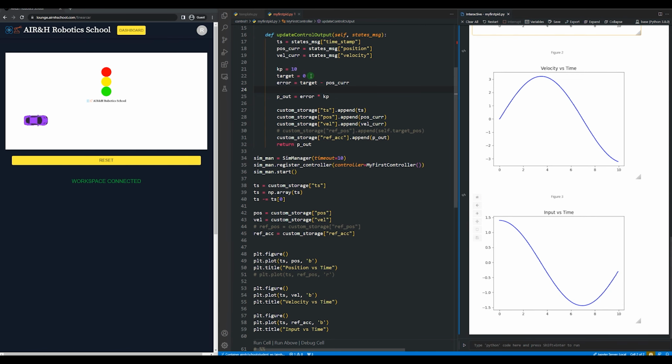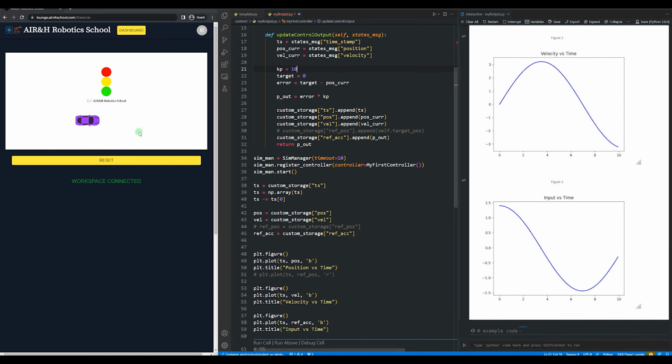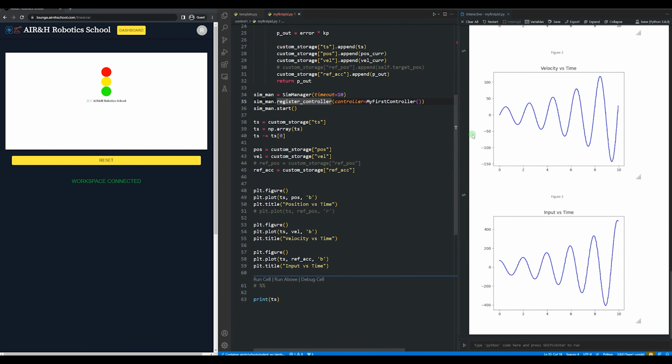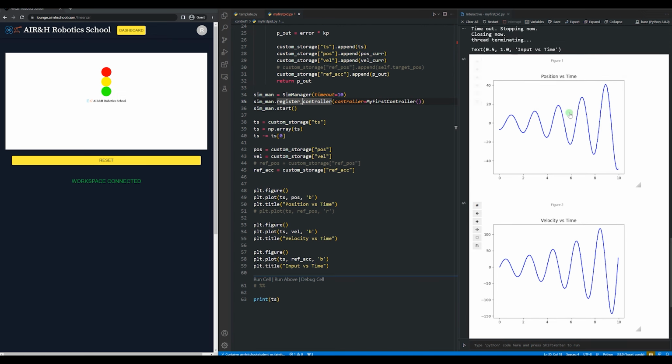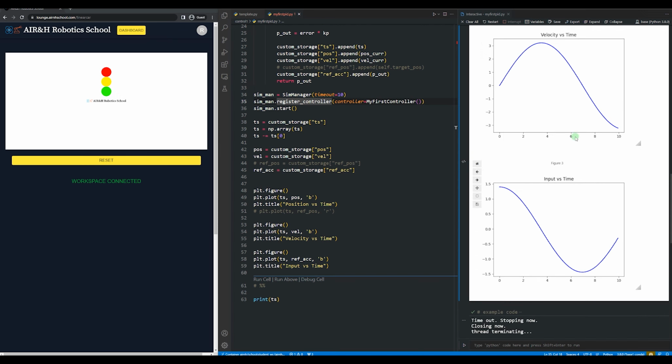And now I want to see what happens if I increase the Kp to, say, 100. It's way faster, way faster. And then, whoa, what is this? This is exponential growth with oscillation. That's velocity, and obviously the velocity was exponentially growing with oscillation. The position must be growing as well. And way faster, and then the period is shortened compared to the previous Kp.